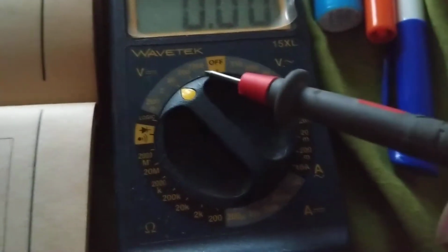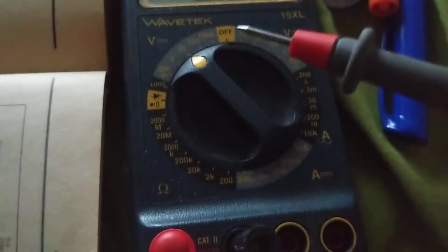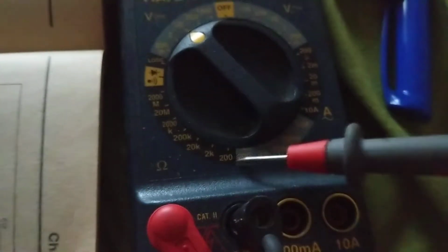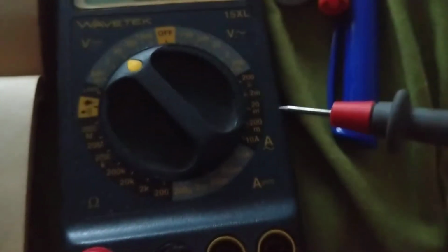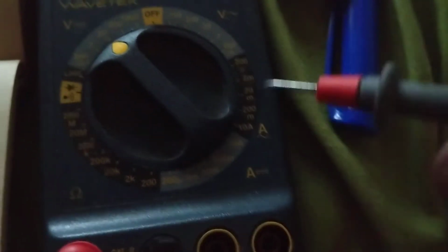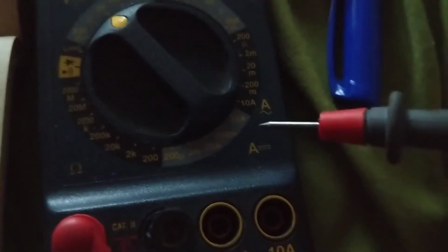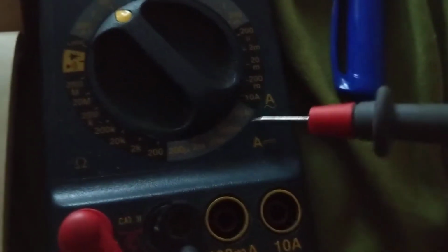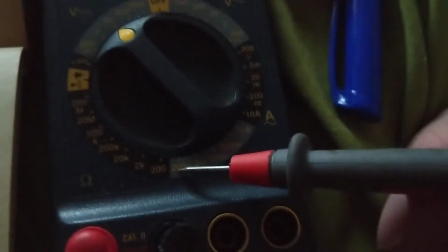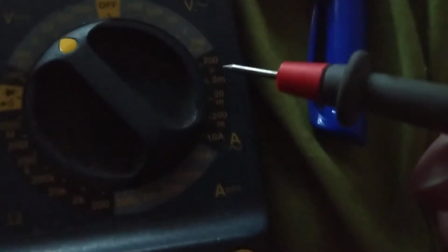Let's look at the meter. We know volts; this goes up to 1,000 volts. This signifies DC, the straight line. This signifies ohms, omega. If I want to measure amps, this signifies amps, but for AC, look at the sine wave. If I want to measure amps DC, up to 10 amps is this one. Anything from here to here is for DC. For AC, anything from 10 amps to 200, and this is micro.